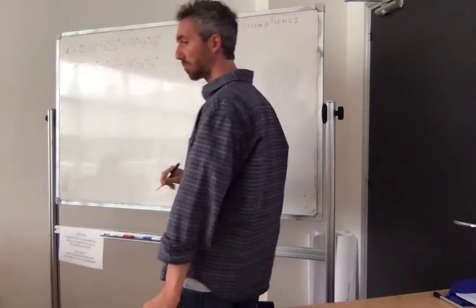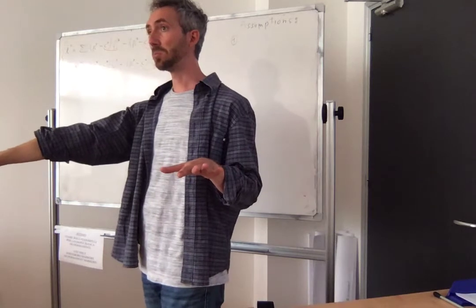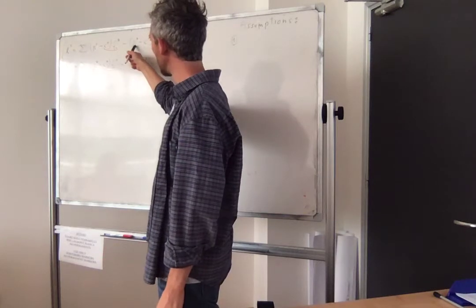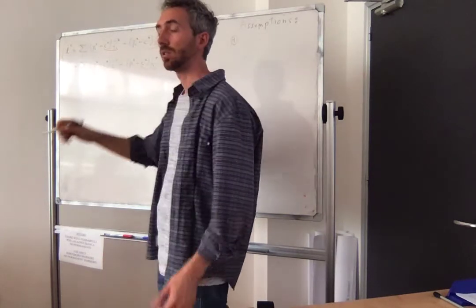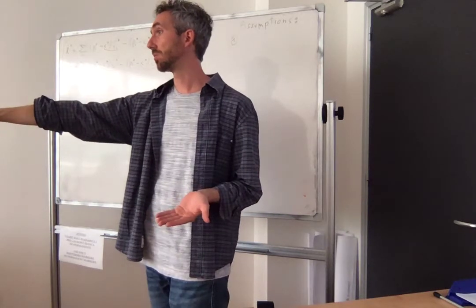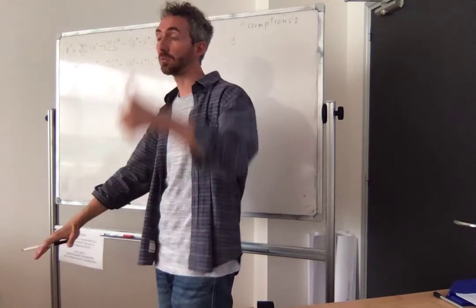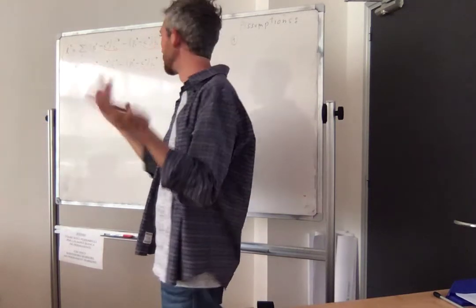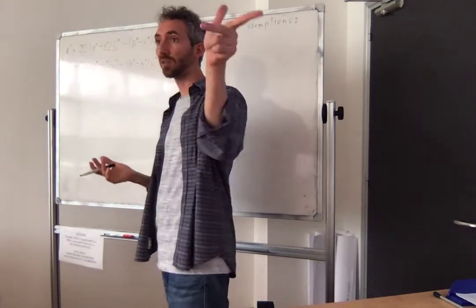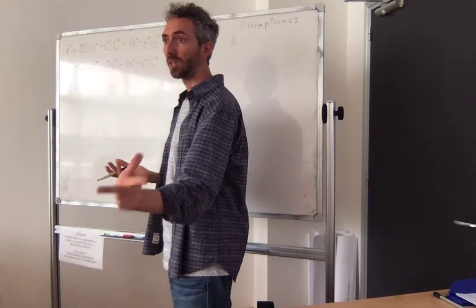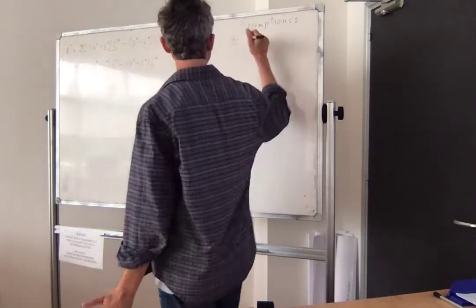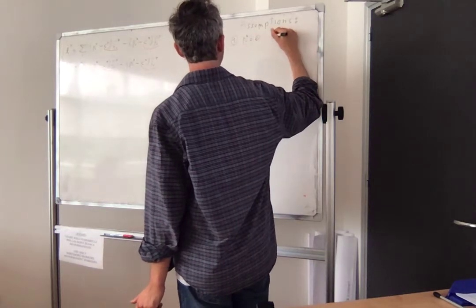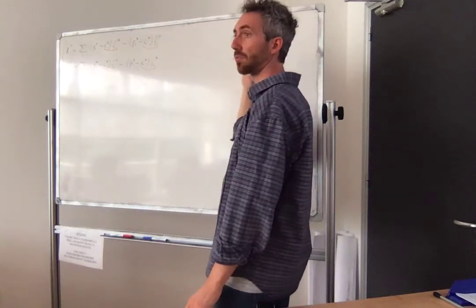First assumption, we are walking on a flat ground. What does it mean in terms of math? That the height of my contact point, Piz, is going to be constant, the same for all the contact points, because z is aligned with gravity. So flat ground means the same z. And since it's the same for everything, and I can put my reference frame wherever I want, I will put my reference frame on the ground so that Piz is 0 for all i. So this means flat ground.